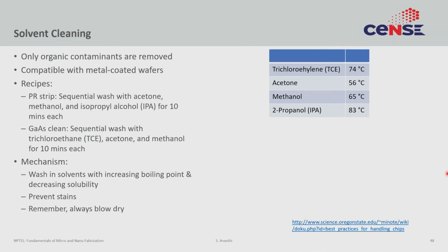The advantage with this clean is that it is compatible with metal. So even if your substrate has metal, you can actually do solvent cleaning, but you can't do any of the other cleanings we have discussed till now because they would react with that metal. The recipe is often used to, for example, remove photoresist.